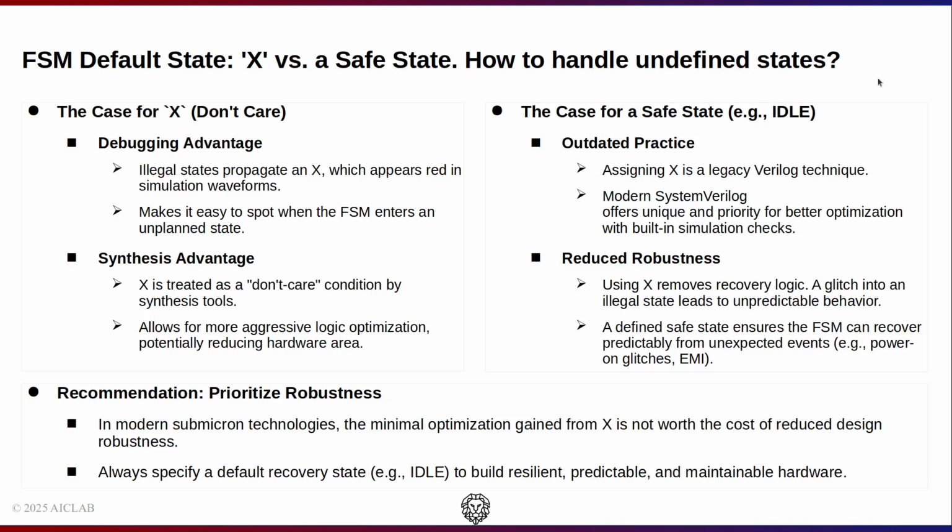Also, some people recommend using a specific state, for example, idle, for default statement. They argue that the X value is outdated and it is used in legacy Verilog code. SystemVerilog offers unique and priority keywords for better optimization. Also, using X value in your RTL code introduces mismatch between simulation and synthesis. Simulation considers X value as unknown and synthesis considers X value as don't care. Also, using X value for default statement reduces the robustness of your design.